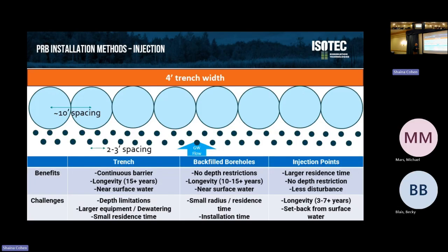And one of the great things about the solid substrates here is being able to go near surface water oftentimes. We're not worried about our injected substrates, we're not worried about an oil, we're not worried about a persulfate getting into a surface water body. But they also do have limitations in their residence time as well. So that's something to kind of offset and where we may need more rows or maybe multiple trenches, depending on what that is.